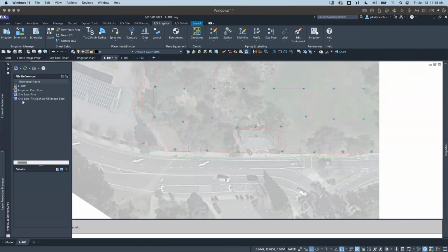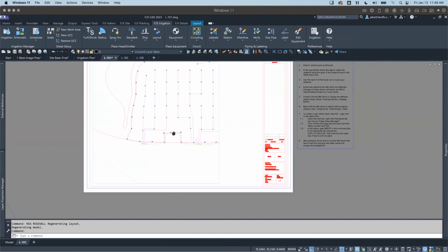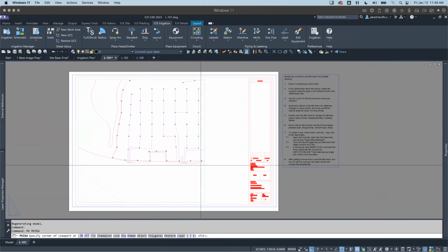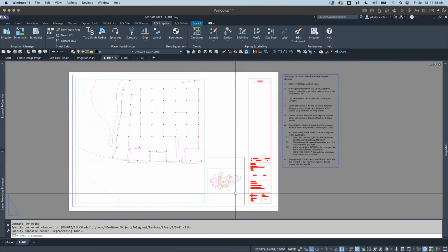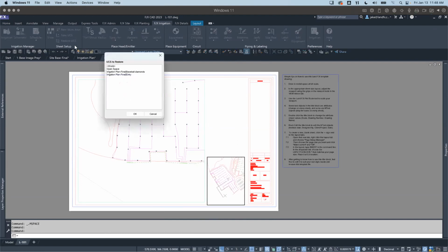I'm going to turn this off for a second. You can see that our line types are appropriate. If I were to make another viewport showing at a different scale, and let's restore this, here's what's really cool about still being able to set a UCS in a sheet layout. We want to do it all in one drawing because we have all of our views and UCS set.